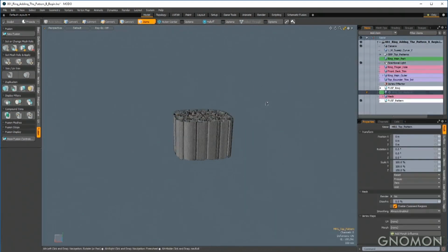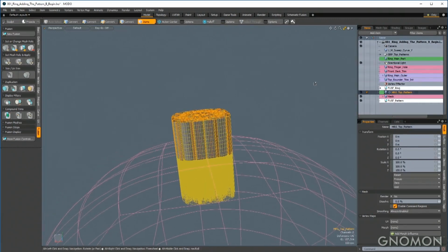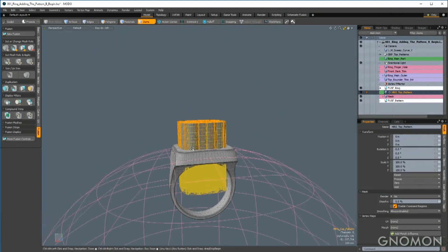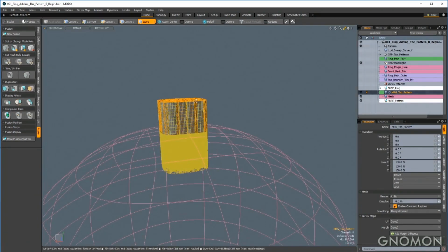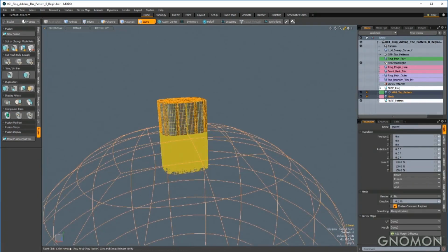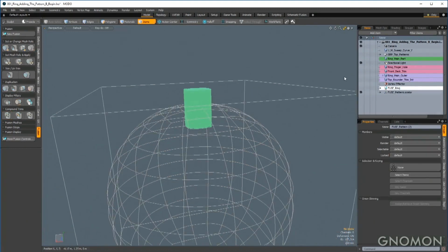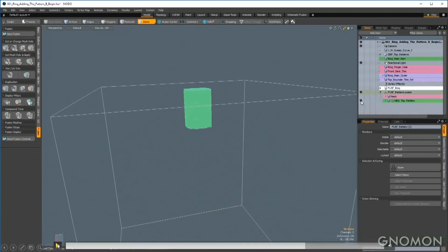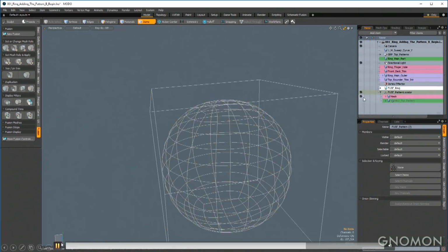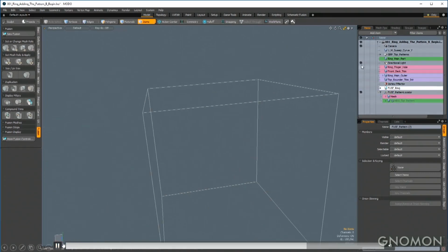I'm going to select either of the fusion sources for the second fusion item, and I'm going to create a compound trim. So in the Fusion Vertical tab, under Compound Trim, I'll choose the first icon, and you'll notice a few things have happened. We no longer have the second fusion item in the item list. Instead, it's replaced with a locator, and the fusion sources from the second fusion item are children of that. And the locator looks more like a bounding box that surrounds the fusion sources.